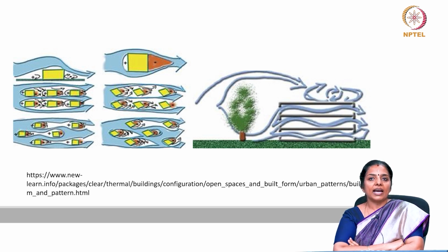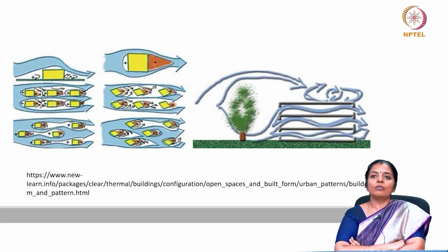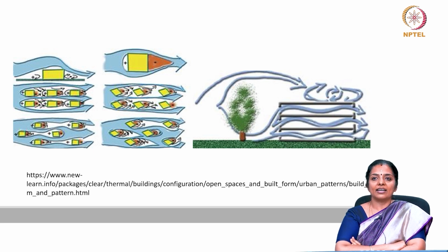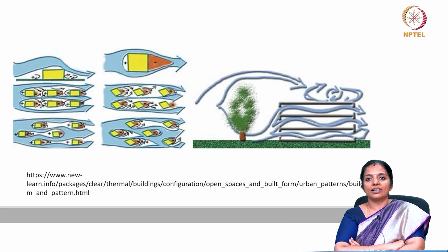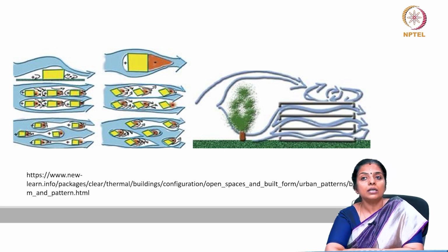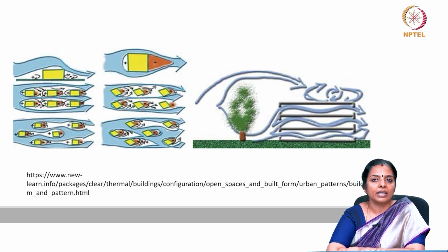The regional air currents flow mainly over the top of the buildings, while in between the buildings, a secondary airflow pattern is created as a result of the friction between the upper air currents and the building. This may be desirable in certain climatic conditions like the cold winters or hot summers when winds are to be avoided, but undesirable in warm humid climate when ventilation is required.